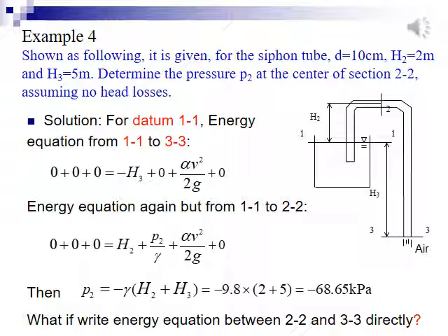From this siphon example, you can see as long as the upstream level is higher than the downstream level, the flow in between can happen. The negative pressure at a higher place is crucial to the flow. So if there's some air in the siphon, it cannot work. That's why we must fill the tube with water before it works.